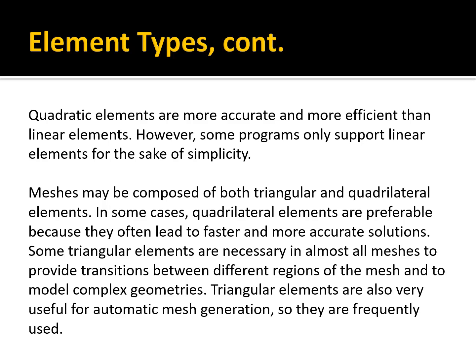Linear finite element meshes are much easier to generate, and with modern computers, it's very easy to get plenty of elements to get whatever level of accuracy you want. So in seepage problems, you can often do both, but we often just use linear elements.